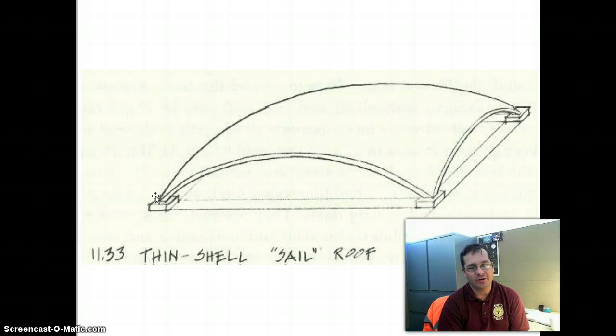Another place you may see shotcrete used is if you have a historic masonry building that's starting to fail. Historic masonry buildings had lime mortar, which is water soluble, and that means that if the building's not been maintained over the years, the exterior load-bearing walls are going to be in a state of disrepair.